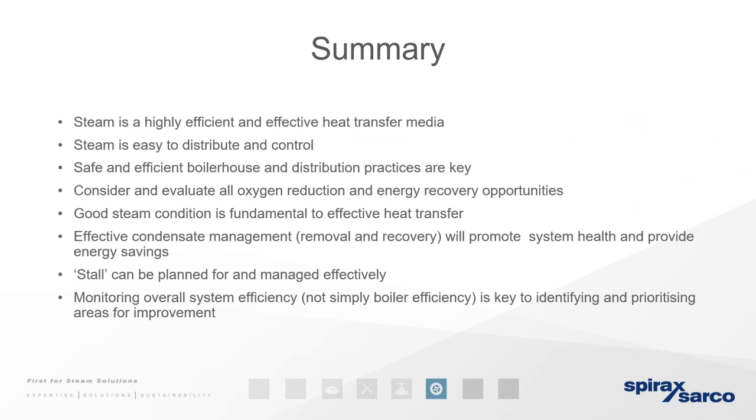We have to consider and evaluate our oxygen reduction and energy recovery options, as we have now rightfully seen that by recovering energy, we can save a lot of money, not just water, but also the energy within the condensate. A good steam condition is fundamental to affect any heat transfer in the air handling units, the plate heat exchanger, or any heat transfer application medium. The effective condensate management and removal of it will promote system health and absolutely provide energy saving.